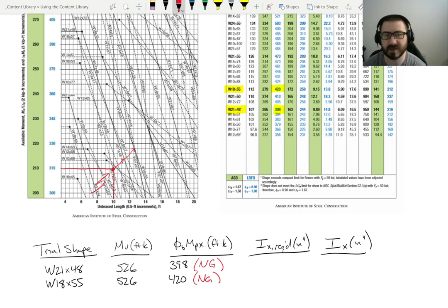The other point I should mention from a previous lecture, and this is sort of a time travel thing because I'm recording this before I talk about it in class: the solid-lined segments in Table 3-10 are not always necessarily the bold rows in Table 3-2. Most of the time they are, but not necessarily. So can you go off of Table 3-2 to pick a section? I guess you can, but there's a chance you won't find the most optimal selection. And if all it takes is a little bit of page flipping, it's not too big of a deal. Okay, so now we're just going to keep chugging along.